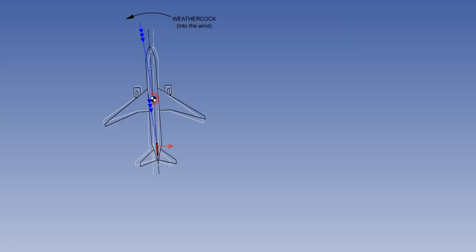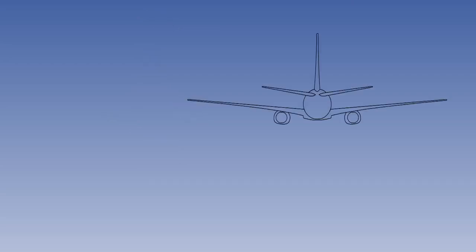For the study of lateral stability, we will concentrate on the rolling moments generated by a side slip. The type of lateral stability is determined by the direction of the rolling moment generated by the side slip. If the side slip generates an unfavourable rolling moment, the aircraft will roll further away from wings level. This is unstable due to side slip.